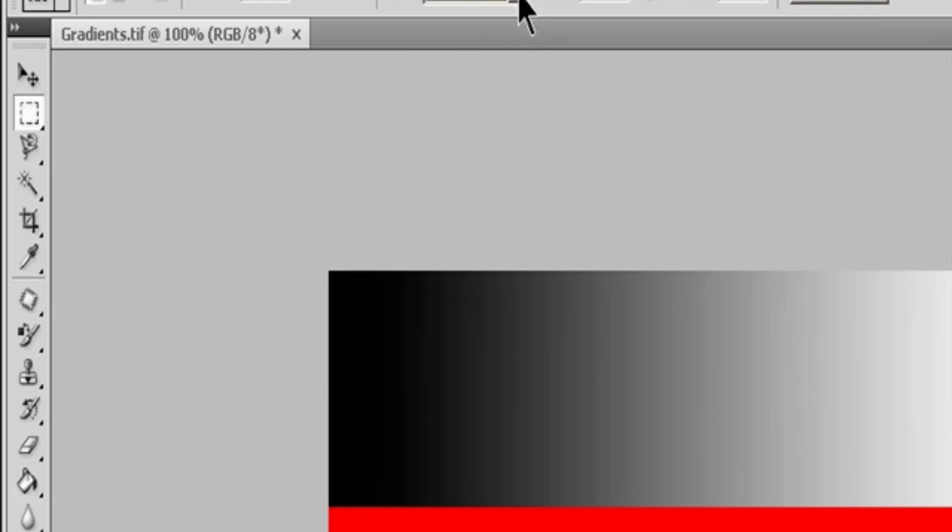For example, to draw a Marquee twice as wide as it is high, enter 2 for the width and 1 for the height. Fixed size specifies set values for the Marquee's height and width. Enter pixel values in whole numbers. 5.